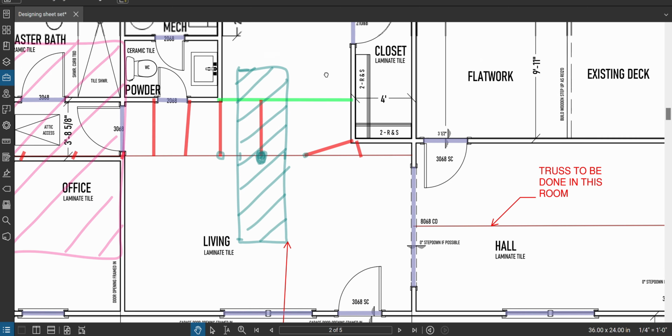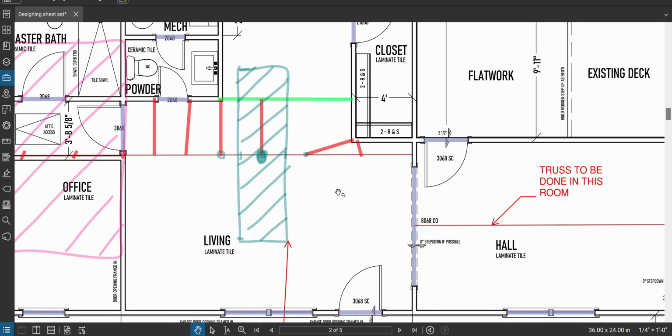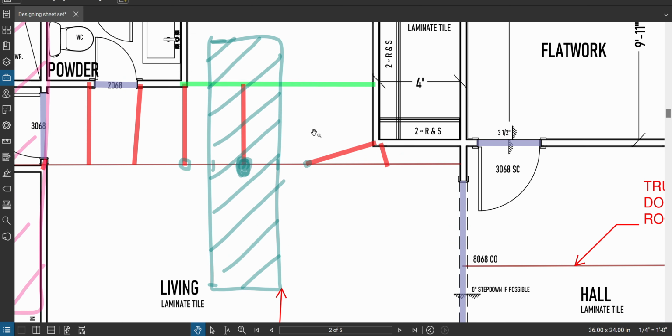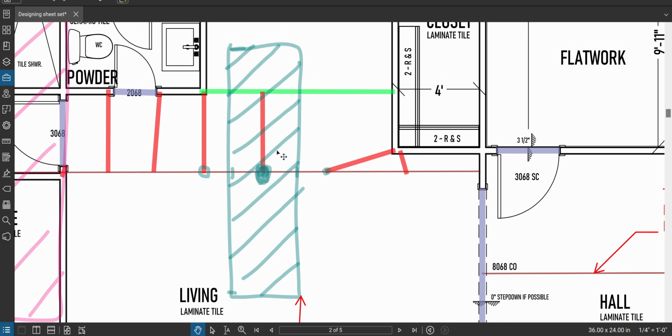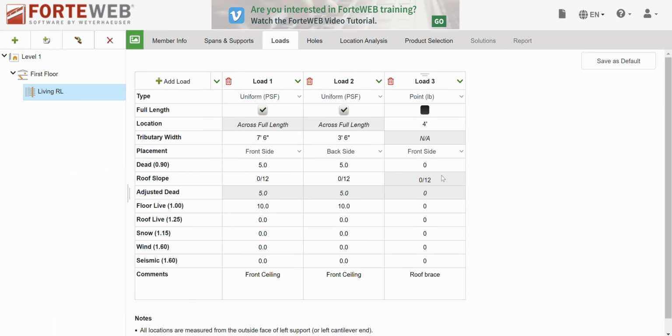Now, how do I get this area into some kind of weight of pounds? Well, I know the typical weights that are assigned to a roof: 10 pounds per square foot of dead load, 20 pounds per square foot of live load. So I'm going to apply those to here. Now, the inputs are separate. Remember the load duration factors I was telling you about? Dead load matters differently than live loads, right?